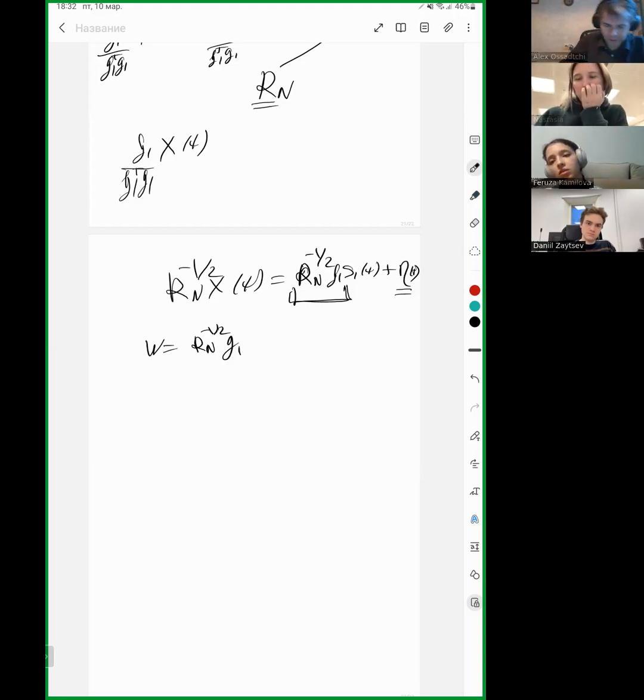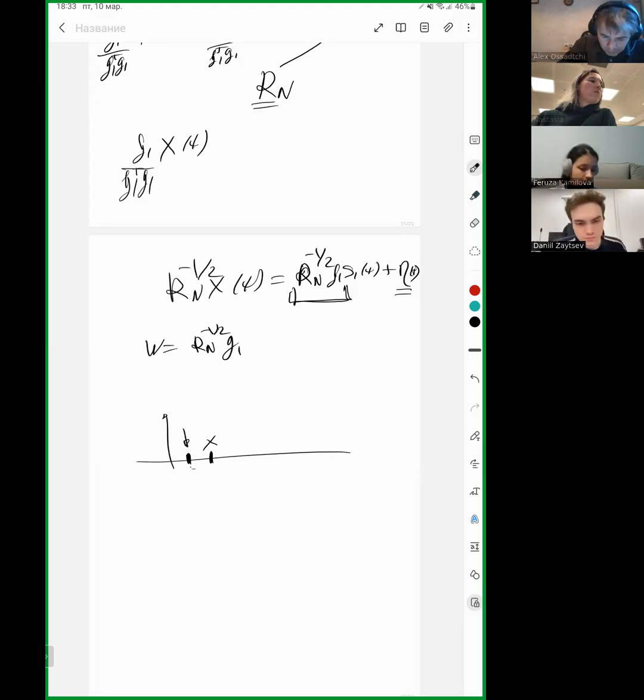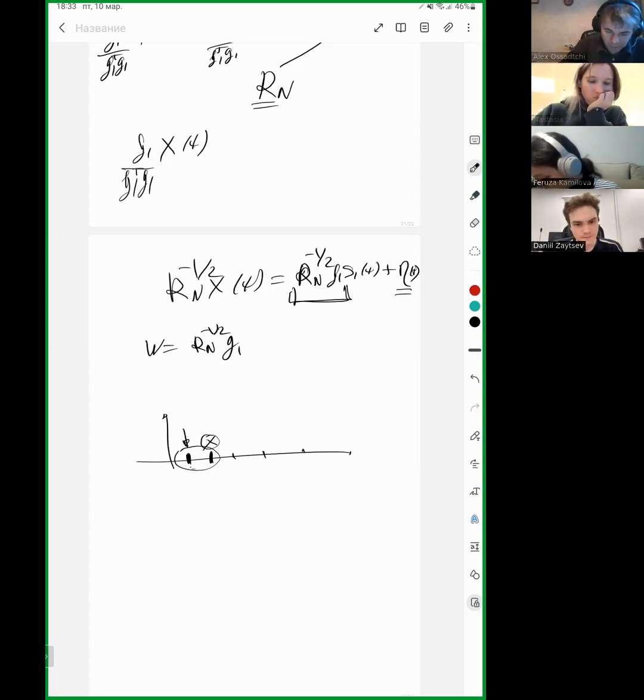You can say that you want to listen to a source that is located here, and you want to listen to a source located here. If they're close enough, then it might be very difficult to listen to this guy and not to listen to this guy. But with beamformers you can do it, because you will not be trying to cancel this source, this source, this source, this source, but you will only be working with these two sources, trying to tune yourself away from this guy and some noise, and tune yourself for this source, right? So that's a general idea of beamformers.